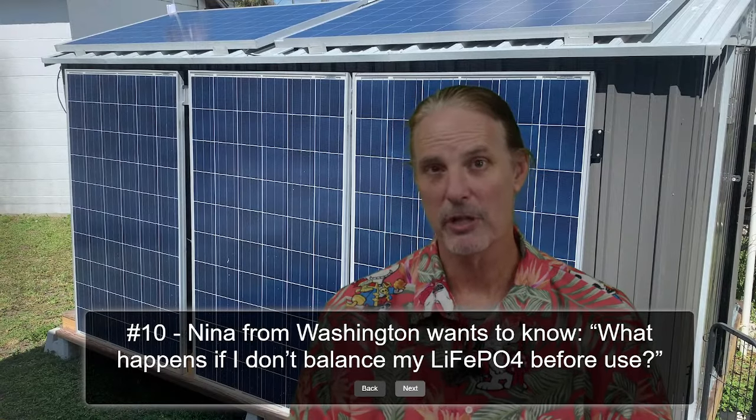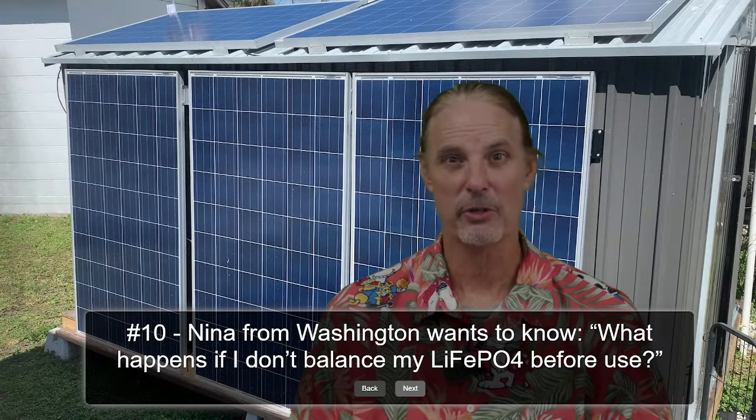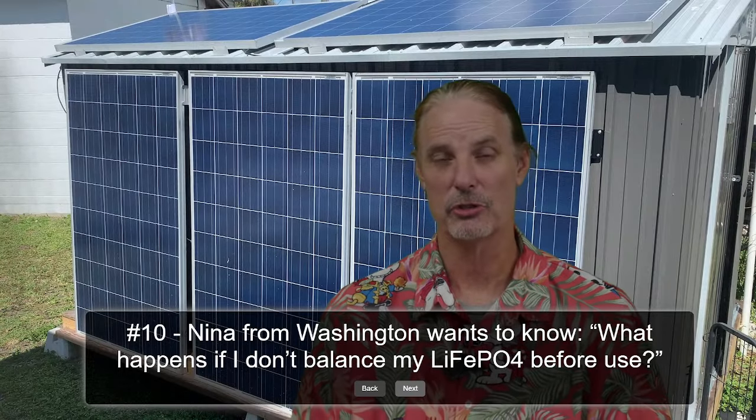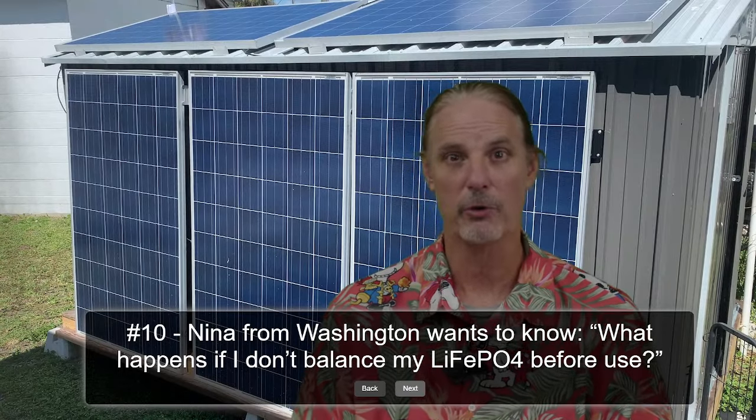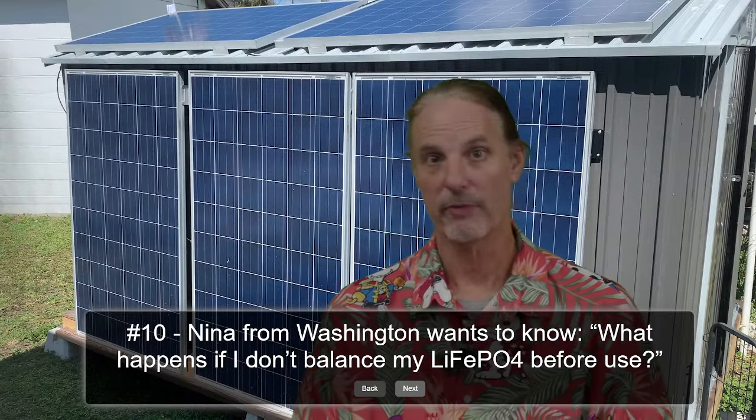If you're adding them to another bank, I'll warn you again, that you do need to make sure that the batteries are within a certain variance of the batteries that you're connecting them to, so that you don't have a large amount of power transferring from your existing bank to the new battery, or vice versa.